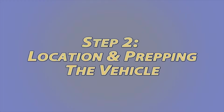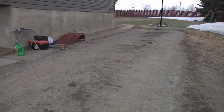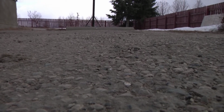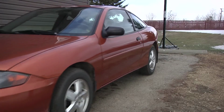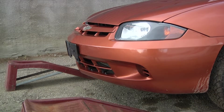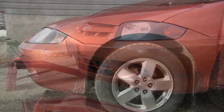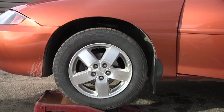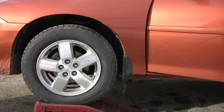Step 2. Location and prepping the vehicle. In this step, we'll set up the location where we will conduct the oil change. First, locate a flat, solid surface, preferably paved or a garage. For this, we'll be doing the oil change on a paved driveway. Start by lining up the ramps to the vehicle's wheels. Drive up the ramps very slowly, being careful not to overshoot the ramps.